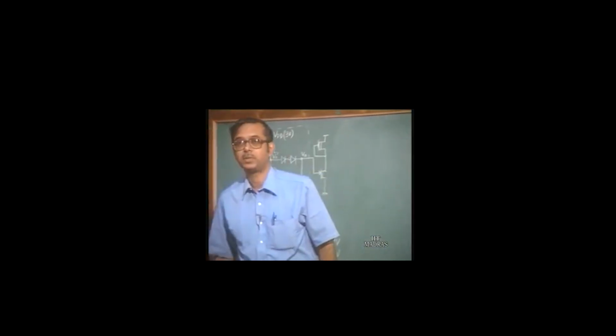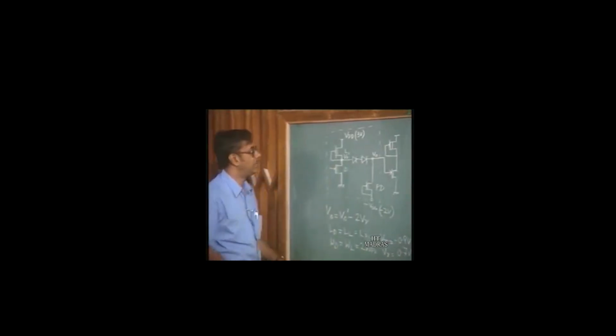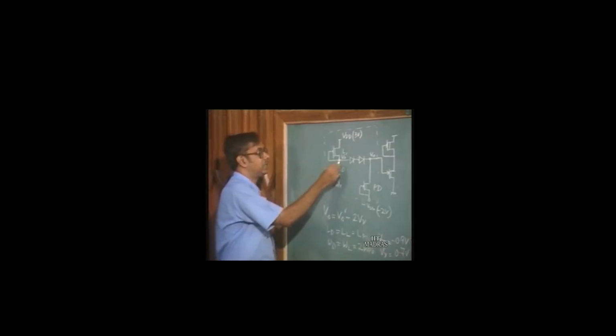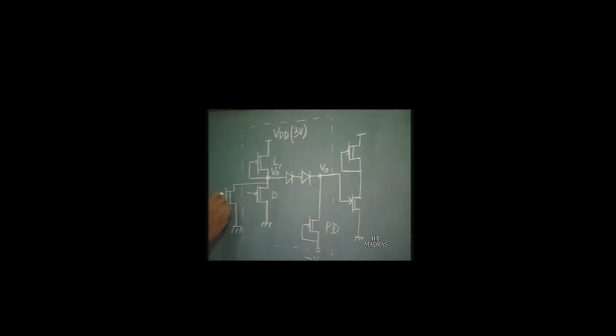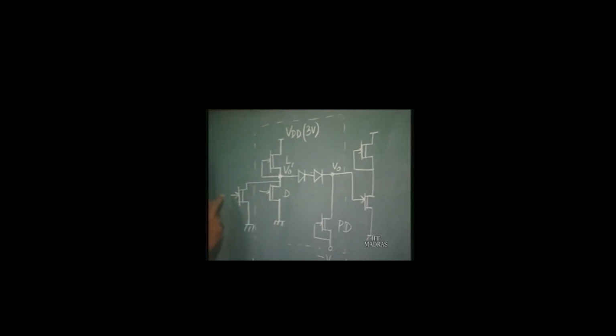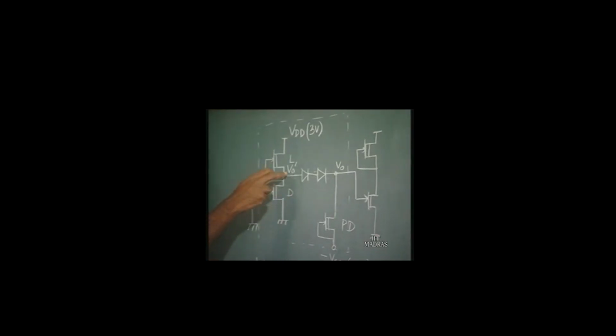So, we have seen the inverter structure for this particular logic and seen that its input output characteristics behave as an inverter. So, if we want to make a NOR gate from this inverter, we follow the usual procedure, that is we have another similar transistor in parallel with the driver transistor, and so when any of these two inputs are high, the output at this point is going to be low. So, which means that it follows the NOR configuration.